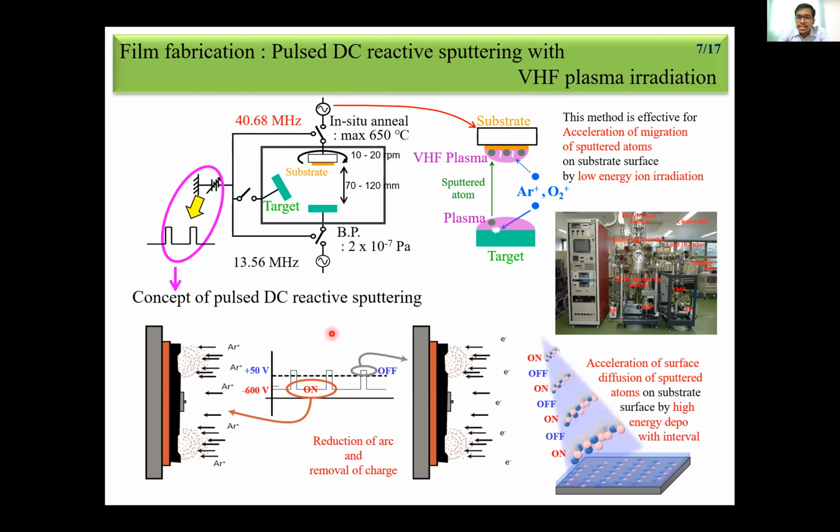And the second important thing is that when the target atoms are moving towards the substrate, they may undergo bombardment. But if we allow only a few atoms at a time, the first bunch of atoms will settle down on the substrate by searching for their potential positions, then the next bunch of atoms will settle down. Like that, we can get very good crystallization. I will show you the proof of how it gives highly crystallized thin films.